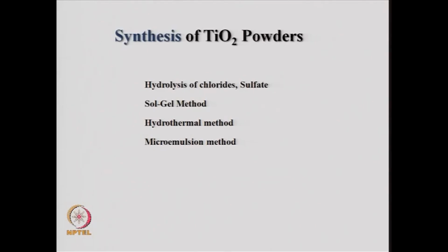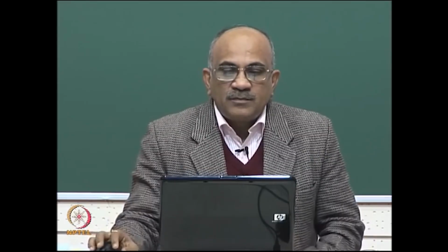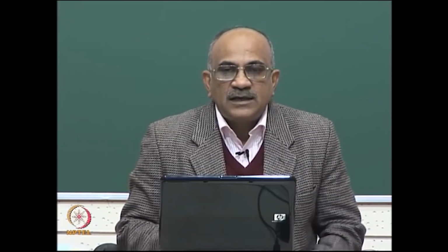Depending on the type of surfactant and solvent, you can control the size of the nano reactors, and then you can do reactions using the titanium salts and hydrolyze them within the nano reactors to give you nanoparticles of TiO2 which are of the anatase form after certain calcination step. So, people have used all these methods to make titanium oxide nano powders in large amounts and in the anatase form.